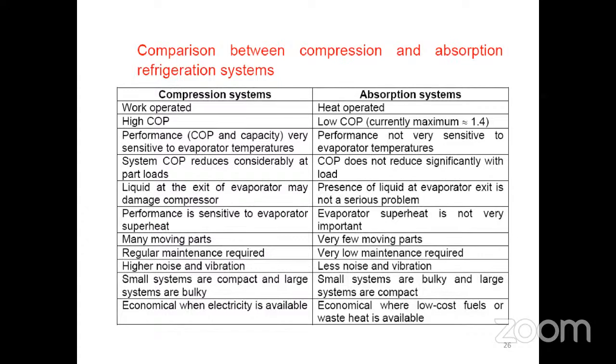System COP reduces considerably at part loads, COP does not reduce significantly with load. Liquid at the exit of the evaporator may damage compressors, presence of liquid at evaporator exit is not a serious issue.